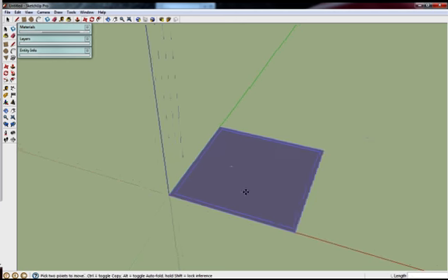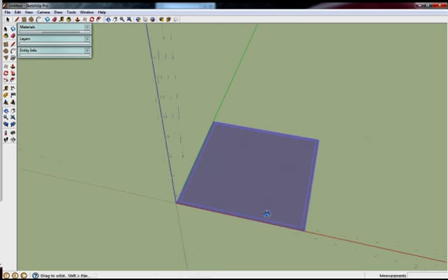Let's get our pencil tool, the L key, and divide the space into 4 equal parts. Find the center of the line made by the inside of the outside wall. A light blue dot will appear. Click and draw across to the center of the opposite line. Do this again on the walls perpendicular to the line you just drew.